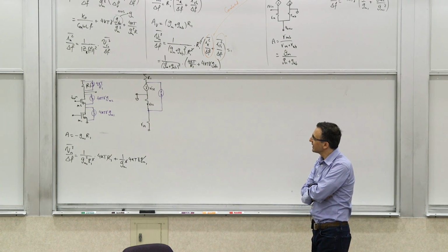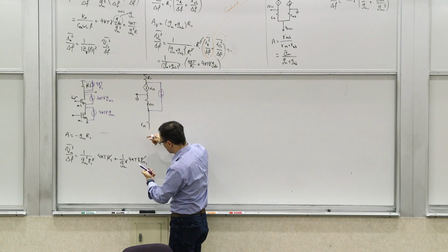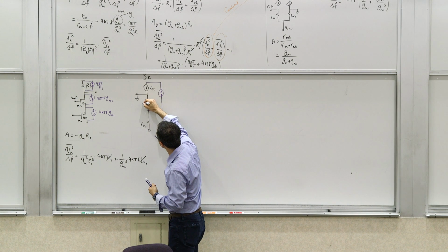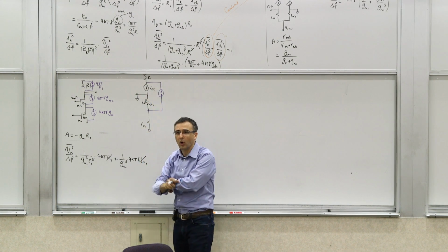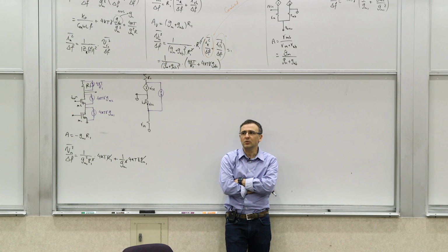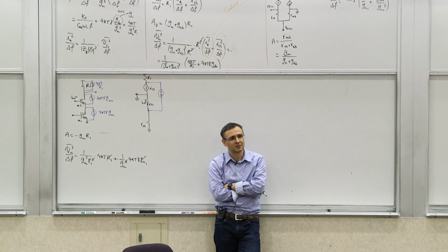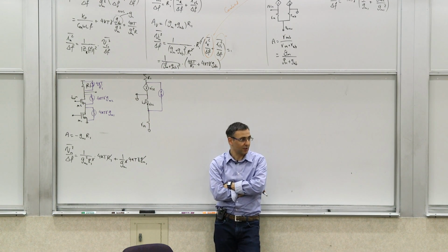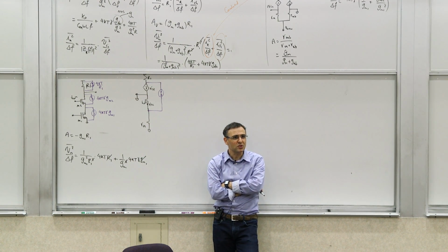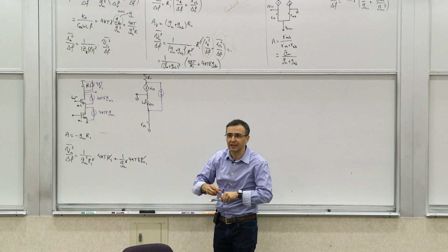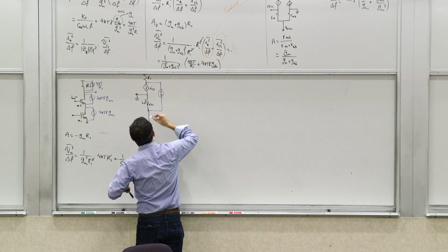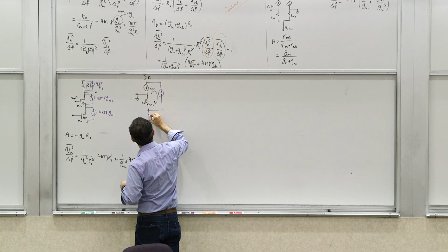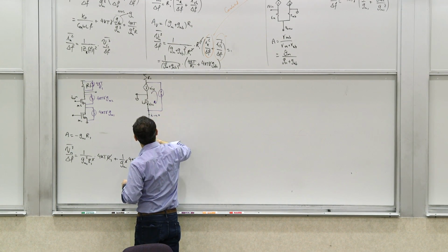You can see that both ends of that current source are grounded, so there's a current divider between these two resistors, RM2 and RO1. Where would most of the current go? RM2, exactly, because it's much smaller than RO1. So most of your current is circulating here, and this current is really small.